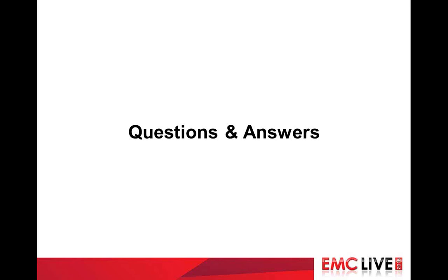The second question I have for you, will the IEC 61000-4-3 standard allow multi-tone testing? Now, George is on Working Group 10, which supports the IEC 61000-4-3. The answer is yes. The 61000-4-3 will allow multi-tone testing. There's nothing in the standard that says that it's not allowed. And again, we are over testing. Everything in that standard is written to ensure that nothing is under tested, but there's no provision saying that overtest can't be done. Again, failure is being defined as a single tone event.